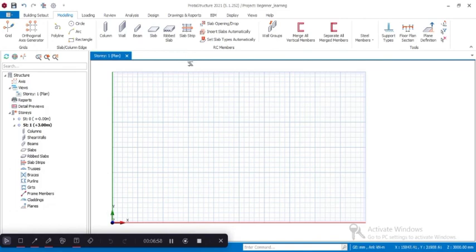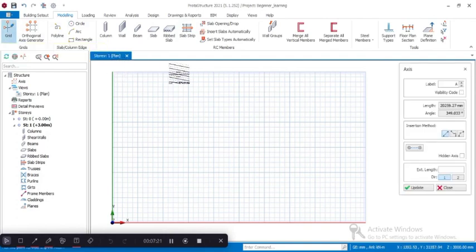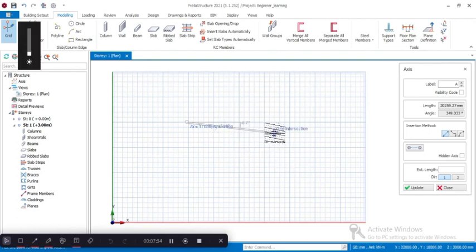During the rubber band operation, the length L and the local angle will be displayed. In addition, the relative distance delta x and delta y, with respect to the local ECS, will also be shown. Press F2 to enable input of the length of the axis via the dynamic input system. So if we have this point now, for us to input the specific length we want, click on F2.